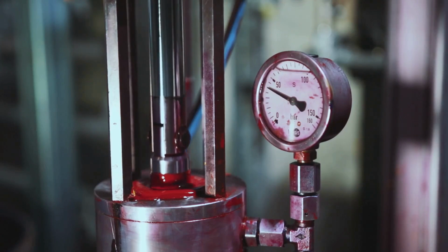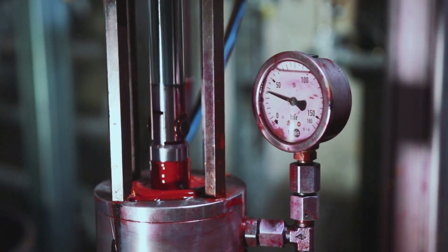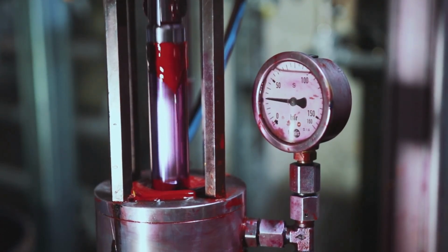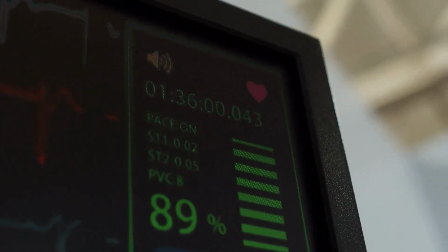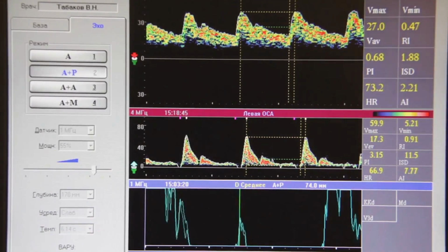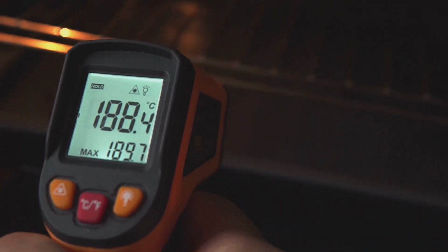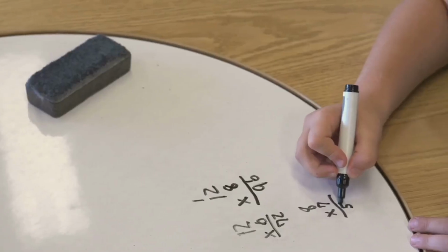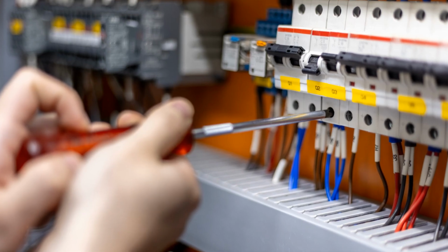Observe how quickly the process variable, PV, approaches the set point and whether any overshoot or oscillations occur. The goal is to find a KP value that provides a fast response without excessive overshoot. Document observations such as rise time, settling time, and overshoot. This documentation will be invaluable as we fine-tune the other PID gains. Once we've established a reasonable baseline with the proportional gain, we can move on to fine-tuning the integral action.